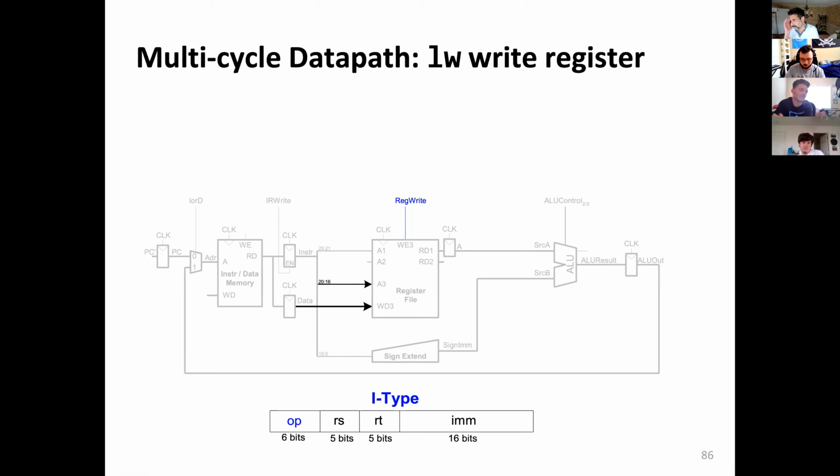Yeah, but it would be analogous to using the set on a flip-flop. You know what I'm saying? Because there are different functions for a flip-flop, like which one of those functions you're activating. Yes. So here, each of these flip-flops has its own control signal, right? You see the clock, meaning that by the clock you should store it, on the positive edge of the clock, right? So the right control signal will be sent to these flip-flops, right? I think you might be asking a different question that I don't get, but let's discuss it at the end when we are done.